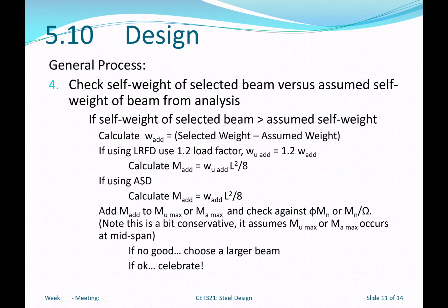If the problem says dead load is included, then you're off the hook. But if you had to assume some sort of dead load, you have to verify that the dead load you included was adequate, or if you need to add some more.